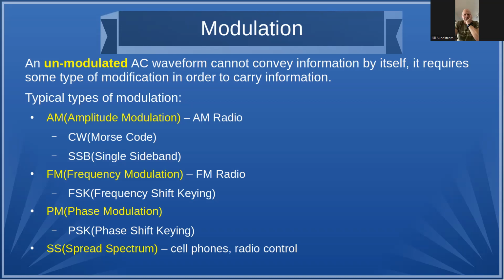A special case of amplitude modulation is called single sideband. When you generate an amplitude modulated voice signal, you get the combination of the carrier signal plus an upper and lower side, what we call sidebands, which are equivalent to the baseband signals shifted in frequency. So one is slightly above the carrier, one is slightly below the carrier. You get that by doing the cross product of the two frequencies. If you multiply the math out, you'll see that you get those three frequencies out: the carrier plus and minus the baseband signal.